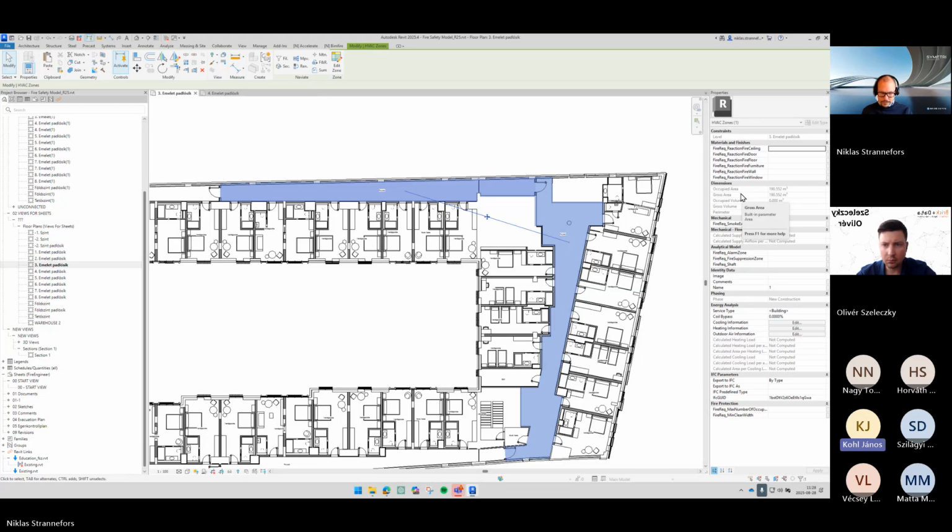Mostly we count by the furniture. So it's kind of different. Otherwise, you can calculate that each person within these kinds of rooms should have 2 square meters and just divide. It's just a quick formula. But we can do that as well using these zones. And then you can obviously place a tag that reads this information, so it's live.